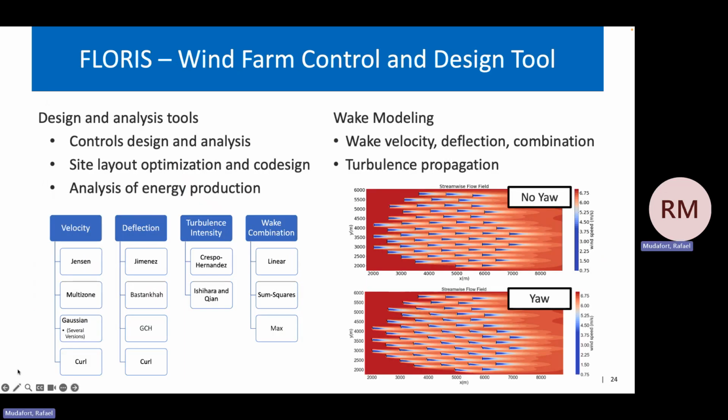All right, and then we get into FLORIS, which is an analytical system for designing wind turbines. So it's very fast, but it's not extremely high fidelity. Like I said, lower than OpenFAST, but you can do a whole lot of simulations very quickly to get an optimized wind farm layout. So this could be used as a starting point for FAST.Farm.